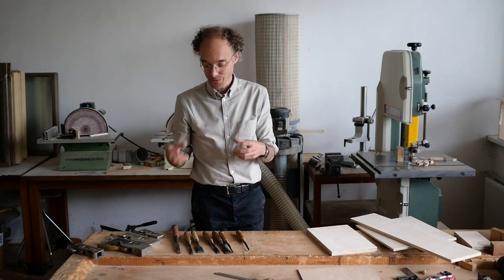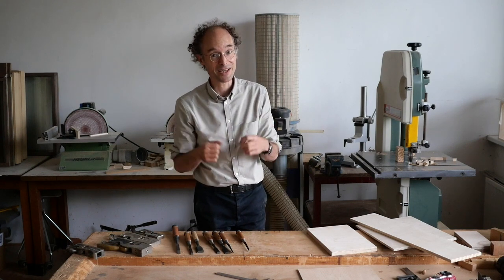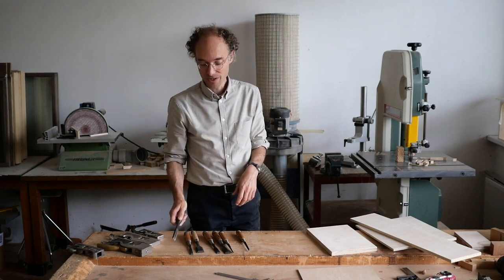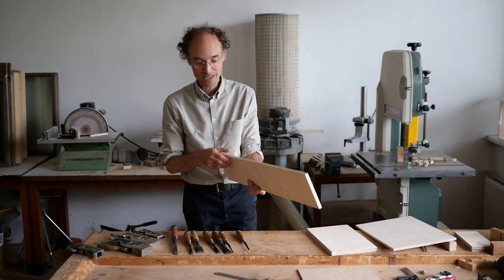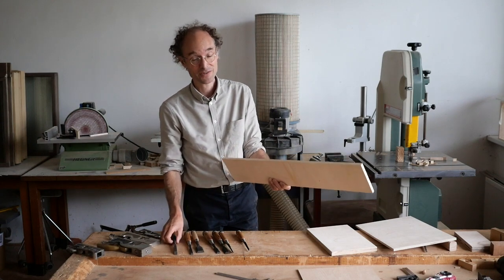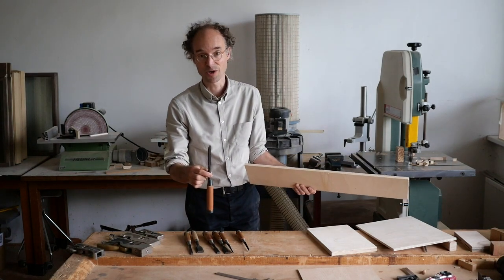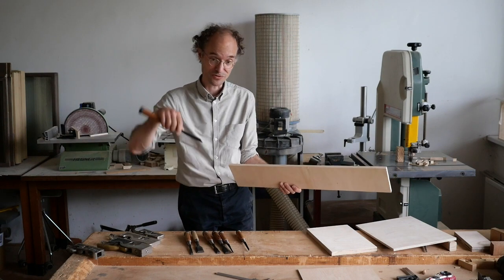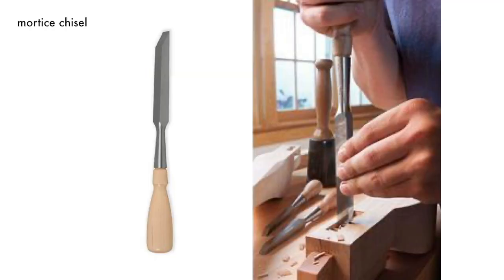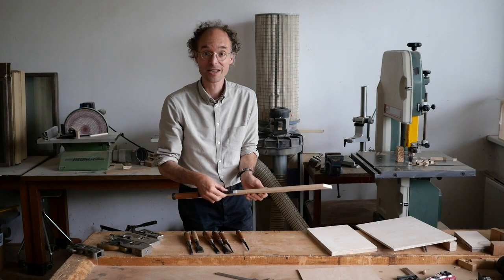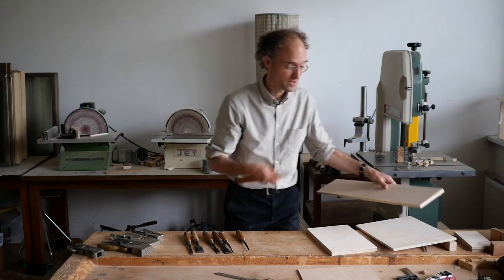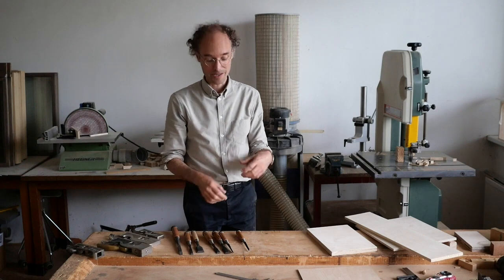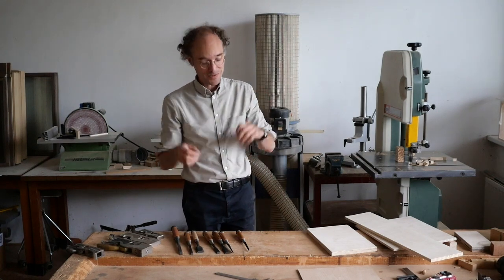If I have a chisel which has the thickness of the tenon I'm already making, I don't have to measure anymore. So I would have material of half a unit, half an inch in this case, 12 millimeters, and I have a chisel. This is especially a mortise chisel, a very heavy chisel for chopping mortises. If I have a chisel which is exactly the same thickness, I don't have to measure, and I don't have to adjust the sizes of the things I make. So these measurements and these inches